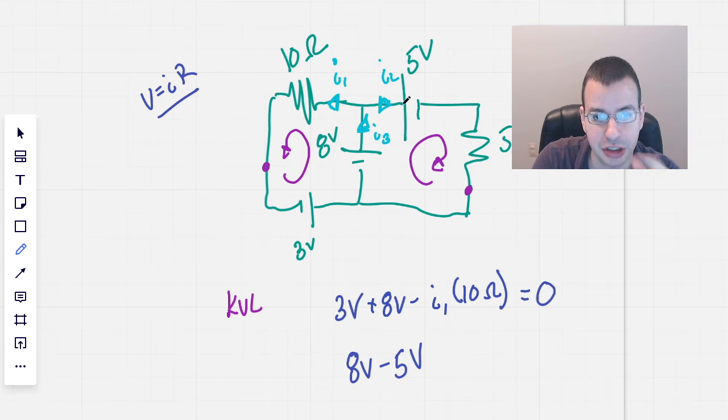We then come to the resistor, and this is going to be a voltage drop. The reason we know it's a drop is because we're going through the resistor in the same direction as current. We're saying that current's going this way, down, and around. Now, we could be wrong, but we're going to assume that we're right for this portion here.